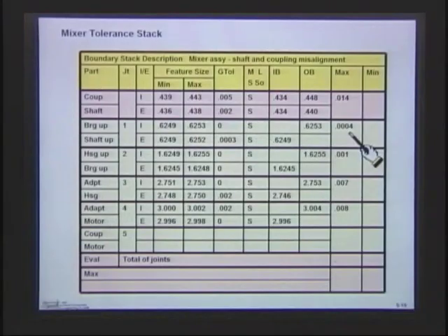Looking back at our chart, you can see the different joints we have. The initial feature gave us a 14 thousandths misalignment. The bearings were 4 thousandths. We had a 1 thousandths misalignment at this joint here. I think that was the bearings again, wasn't it? That was joint number 2. Now some of these are 7 and 8, so we might look back if we need to. All right, let's go on here.